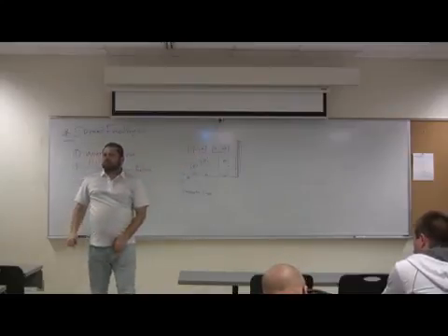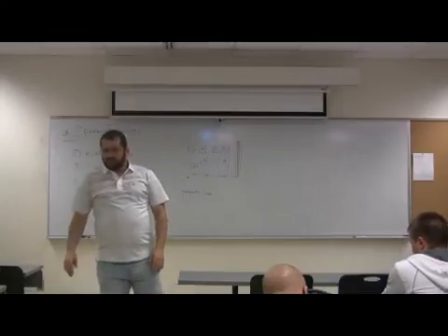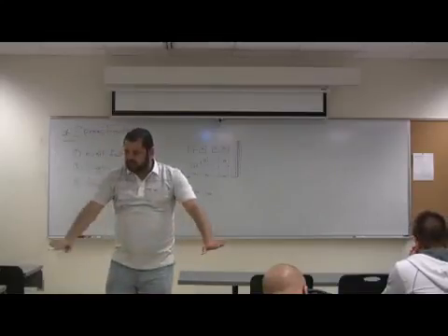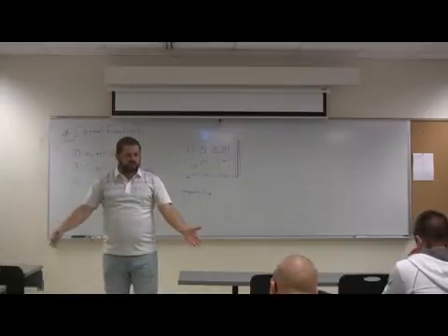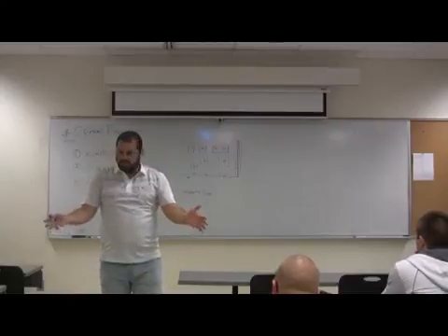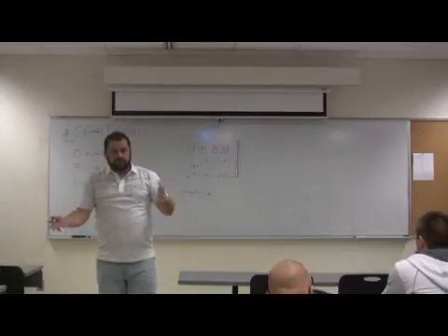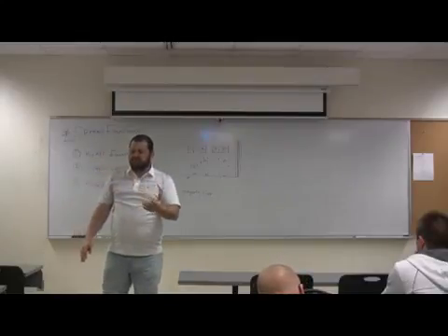There's something sometimes called slab on grade. You know slab on grade? Any slab that has continuous support, continuous base underneath it, that's slab on grade. It's continuously supported. It will not curve or deflect. Usually there is a minimum reinforcement and there is a specification for the thickness.